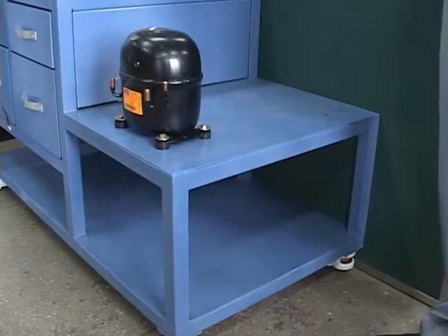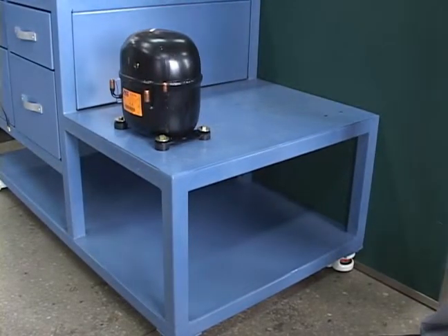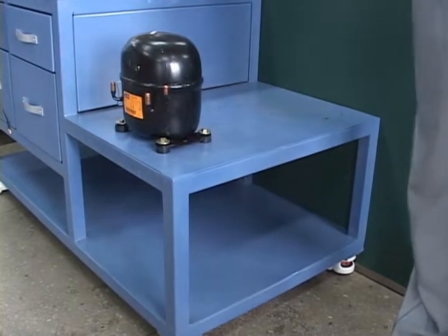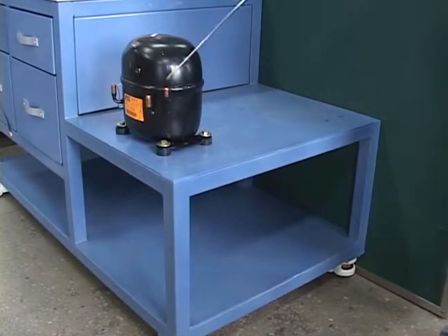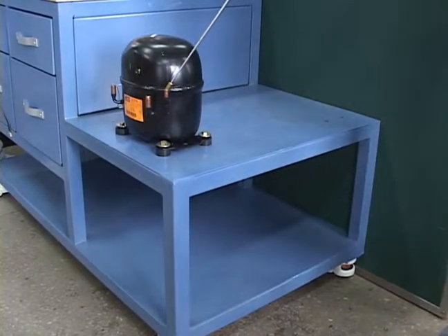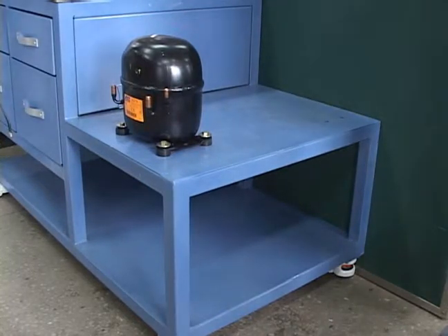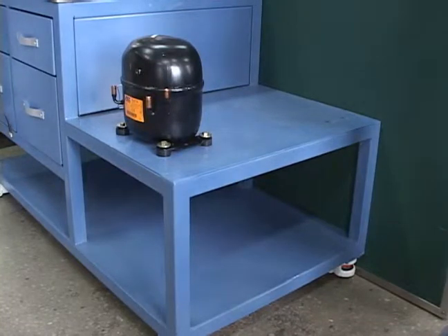The compressor applies adiabatic compression on the low-temperature, low-pressure refrigerant gas sucked in and makes it into high-temperature, high-pressure gas. It is an important process in the whole flow of the refrigerating system. If there is wet compression, the compressor can be damaged. Therefore, caution is required in the system configuration.